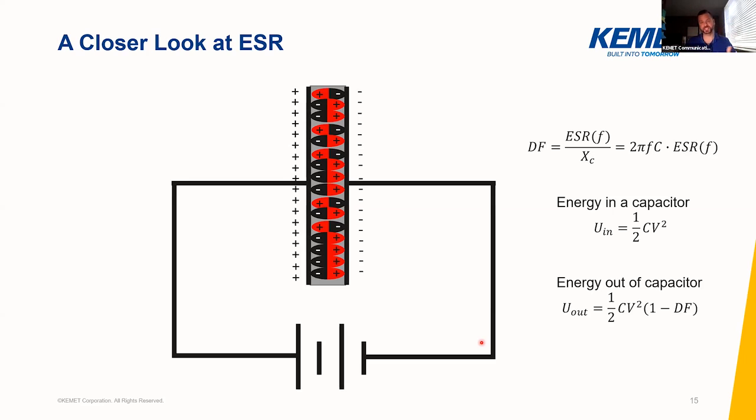But if you're looking at things like really high power systems, really high kVA type of things, kilowatts, hundreds of kilowatts into the megawatts, ceramic capacitors have a much weaker play there and are more in the film and electrolytic place.